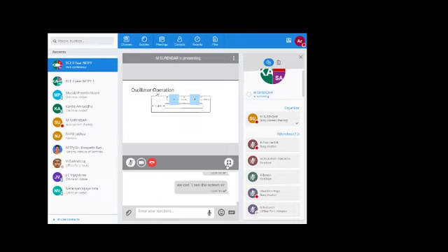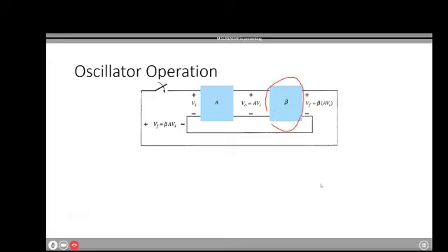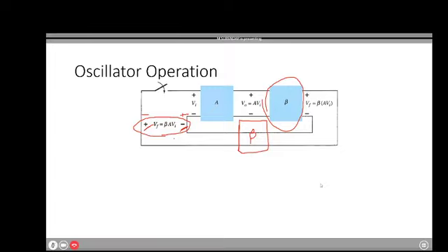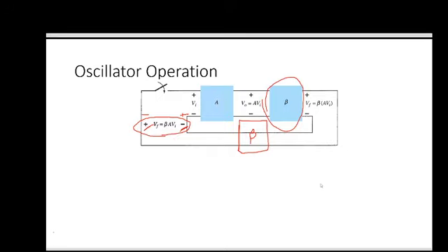So this feedback network is generally connected here for your feedback amplifier, and your oscillator is also no different. The only thing is that VF here is actually minus plus for the feedback amplifier, whereas here it is plus minus. This has to be noticed. This is because part of the output is made in phase with the input signal that we are giving. That is the meaning of positive feedback. And I'm erasing all the ink right now.